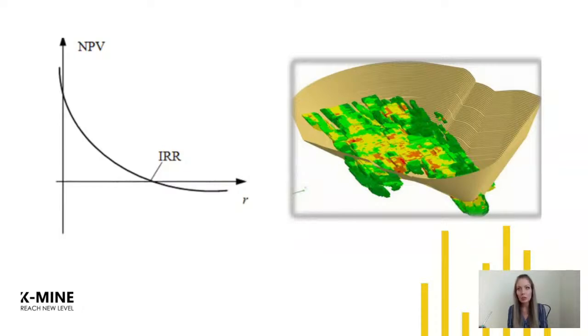The best modeling results are provided when the model parameters like radius of influence or anisotropy, type, and coefficients of kriging equations or other smoothing procedures are selected by comparing the results of model calculations with the results of operational exploration for worked-out areas of deposits.